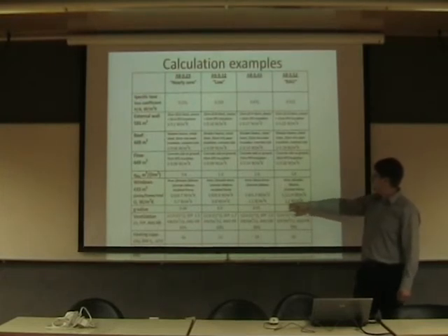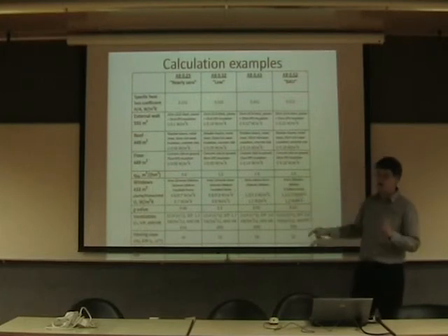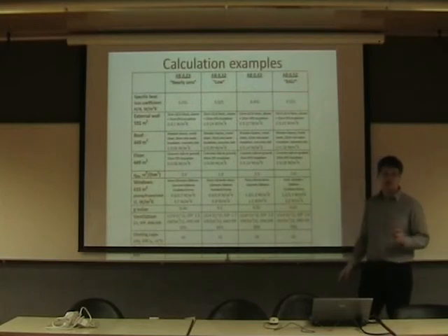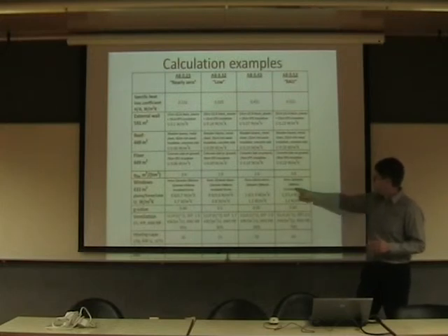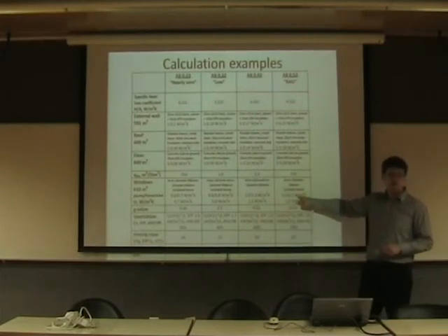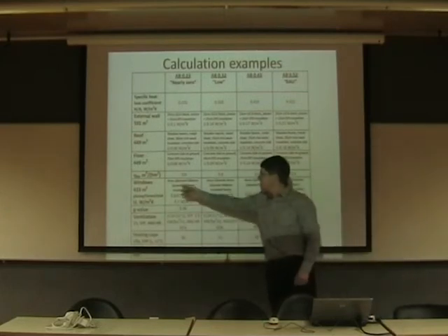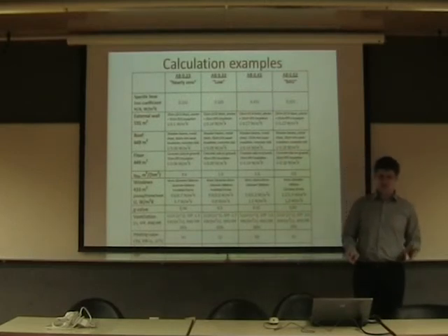And these are the windows. For the regular house, this is the description of the window: 4 millimeter glass, 16 millimeters of gas inside, and one reflecting glass outside, and this U value can be 1.2. This is the glass value, and this is the frame value. And you can also see which kind of glass we can use to achieve this nearly zero energy building.